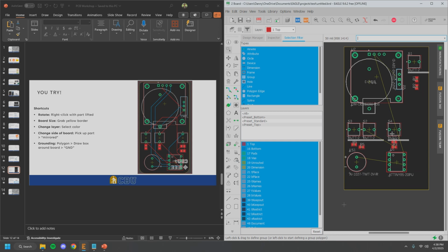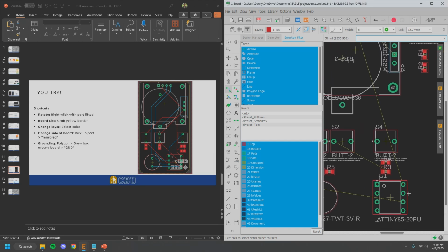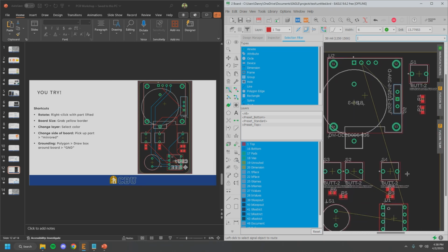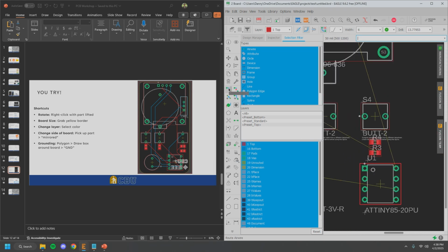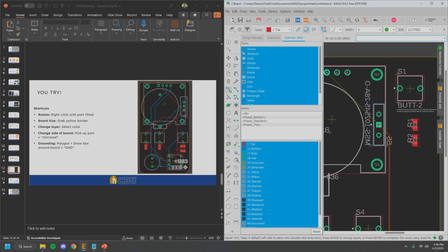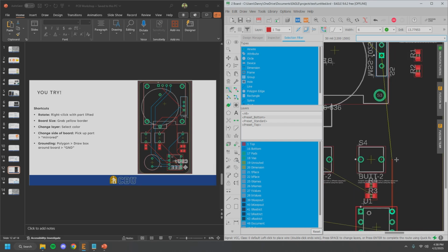And so again, the most important thing on this is actually clicking the Route Air Wire button, and that's how we're going to make our physical connections. If you see, each one of these buttons should be declared as to where they should be connected. And so if I click on a Route Air Wire, click on this, it actually highlights what needs to be connected where, and this wire coming out is an actual physical wire that's going to be printed onto the board like if you were on a breadboard.